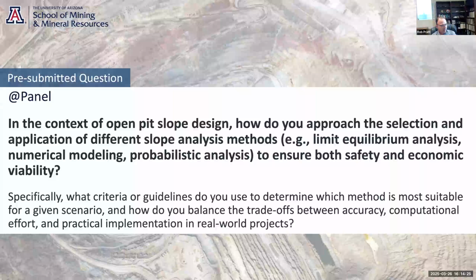And this can be the hard part, where the practitioner has to decide what the standard of care should be for the project, given all those things, and then decide what the analysis method should be. So if it's, say, a large feasibility study for a big open pit with lots of faults controlling stability, that scenario probably lends itself to a big finite difference model. And time and cost, of course, notwithstanding.